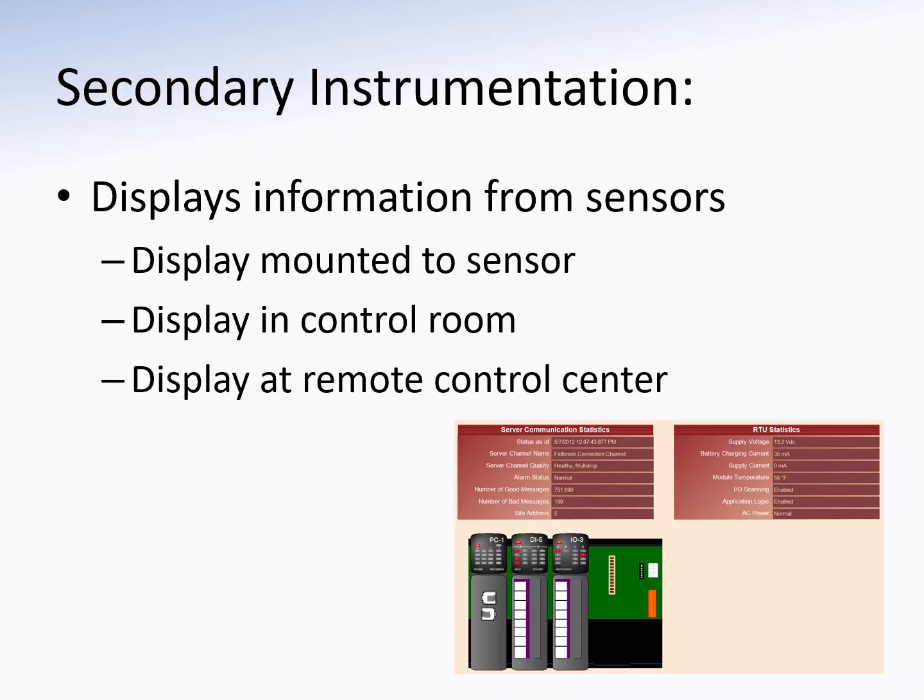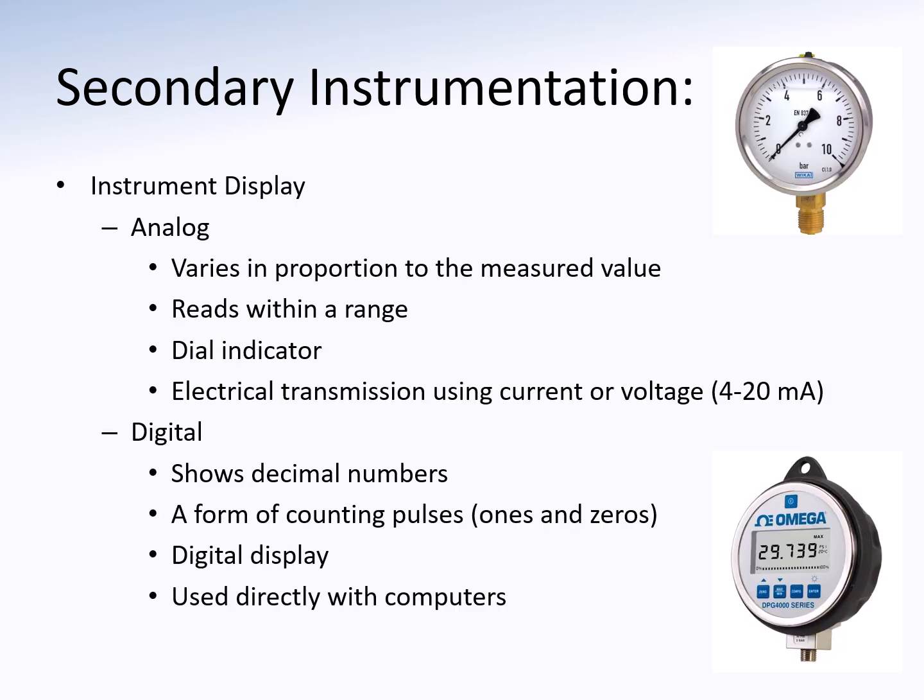Secondary instruments, now, like I said, these are going to display that information, right? So on your SCADA system, anytime you see that, you can think of it as secondary instrumentation. All those primary instrumentation sensors that we just discussed are getting transmitted into your SCADA system and being displayed for you. Another would be an analog or digital signal, right? And so a lot of the equipment that we discussed in the primaries is capable of being displayed in these two different ways.